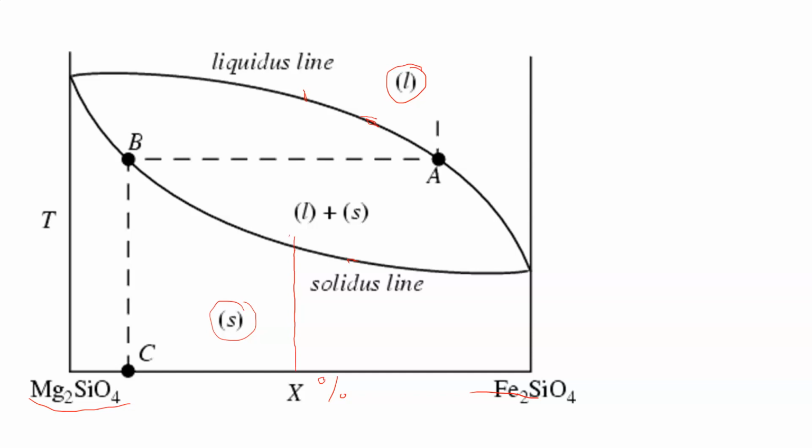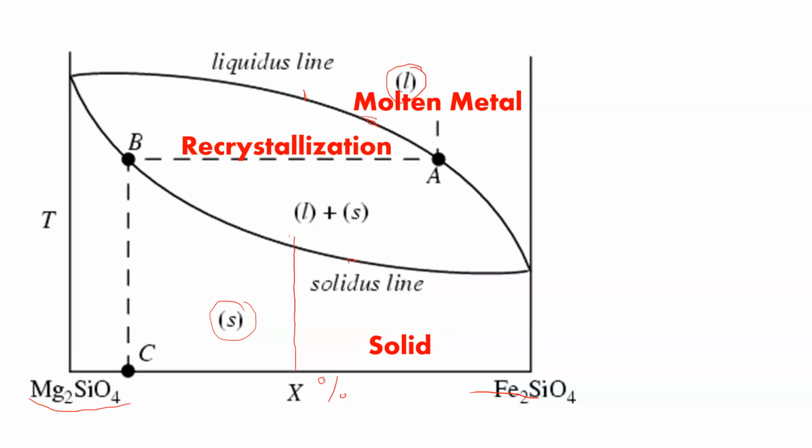recrystallization state. Now, I want to focus in on this recrystallization state because it's very important as far as how joining works. So here, that's the recrystallization state of metal. A lot of things happen in this recrystallization state. One is, this is the state you bring metal to when you want to start doing forging. It's also where you want to start doing heat treating. You can actually change the crystal structure, hence the name recrystallization. It's where you can actually start to promote crystal growth.